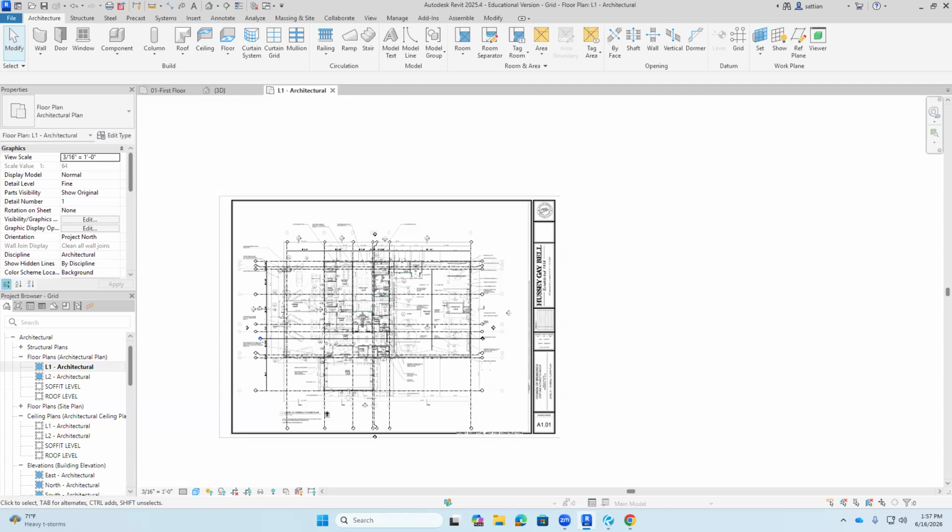But didn't you want to have like... Yeah, I do want the wall type correctly. How do you do that? Edit type, select the wall. Do I have to go in and do every individual one? Yes. Well, not every individual. You do one, and let's say if that wall type is repeated in the building, you just change the wall type to that. But how do you know which one is which? Well, if you look at the drawings, it'll tell you which one is which.